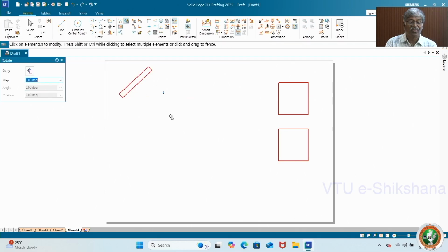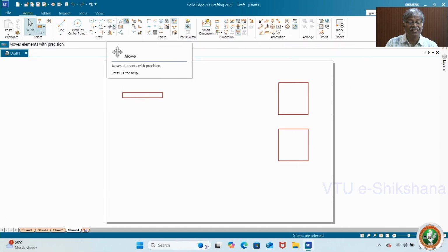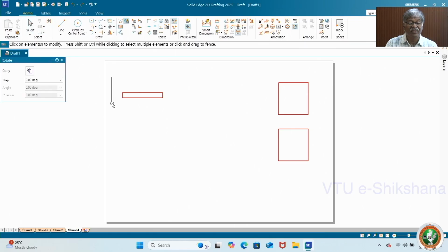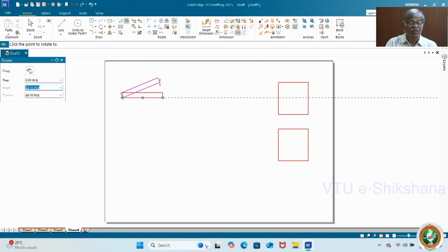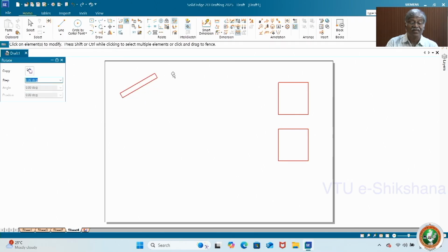Let me do both. Okay. Now I have rotated randomly. Now if you are interested in a particular angle, you can do it. See how exactly I can do it. It's very easy. Commands, rotate about this lower corner, left extreme lower corner, then rotate, okay, by angle, particular angle. See here the blue color is highlighted. So that means it is asking for angle. So 30 degree. If you give 30 degree, you will get. Now you measure the angle.